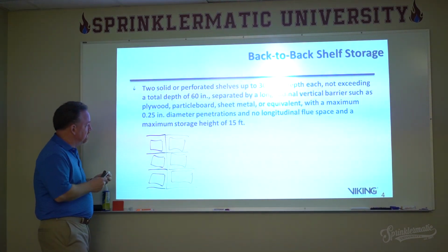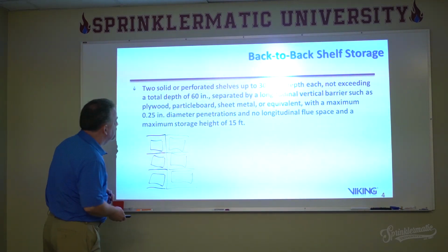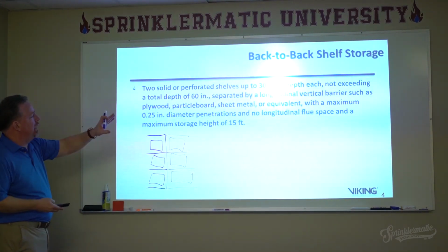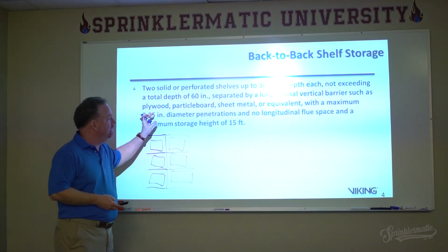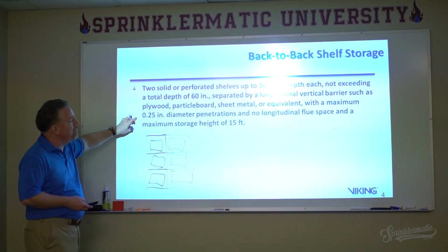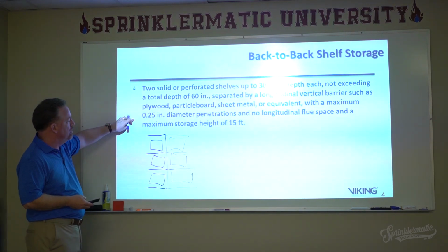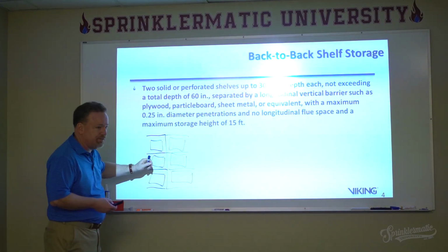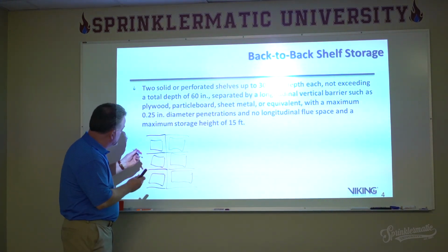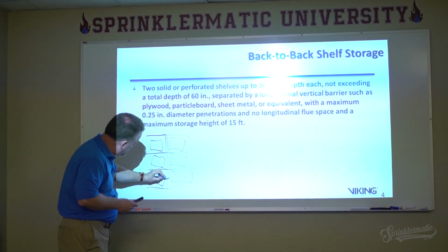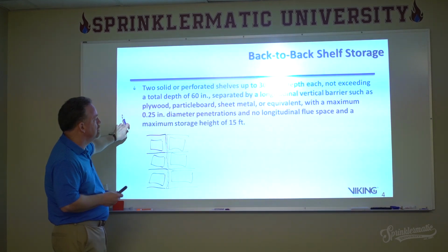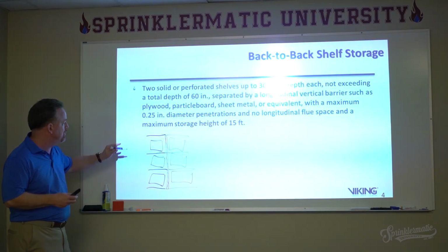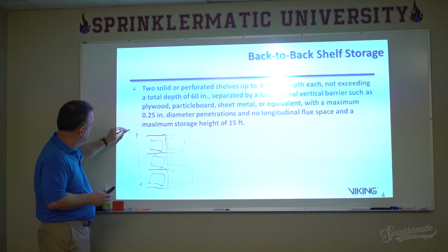Total depth of 60 inches. Separated by a longitudinal vertical barrier, such as plywood or particle board. You can have small diameter penetrations in it, but no longitudinal flue space. All right, we have no air. In other words, we don't have anything in between here. No longitudinal flue space and a maximum storage height of 15 feet.